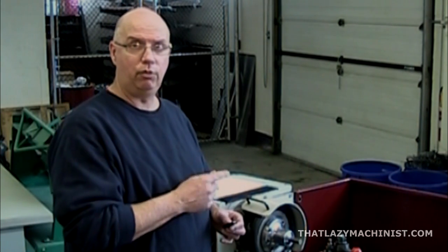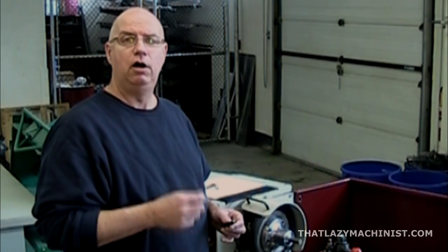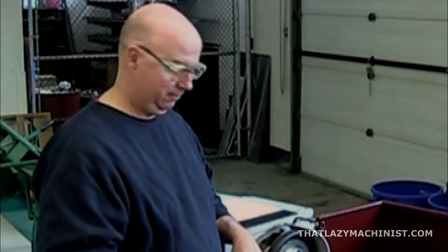The material that we're cutting is a C12L14, or if you prefer, a free machining steel. So, the tool is installed, my RPM, my feed, and my depth of cut are all set. My positive angle tool is ready to cut, so let's take our first cut.